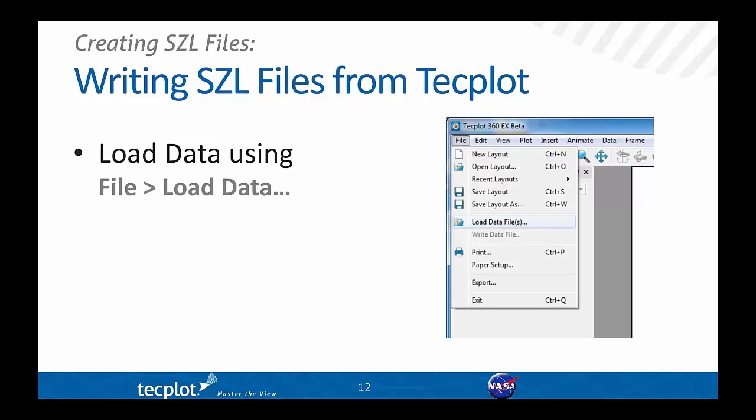You read it in any format you have, except at this point for polyhedral grids. It works with IJK ordered grids. It works with classic finite elements, which in Tecplot parlance would be tetrahedrals, or bricks being hexahedrals.